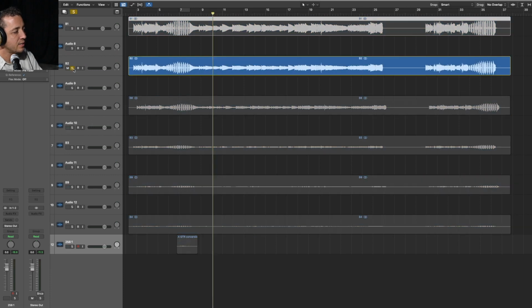This here, well, this is not too bad, but it's still a little bit too hot. You still want to turn it down because that almost clipped. You want to have a little more headroom than that. And right here, it actually did clip. For most of his levels, it's actually pretty good. But you want to have your gain set low enough so that it works for the majority of the recording, and also when they play something extra loud, like in a loud part, you don't clip. That's the most important part right there. No clipping allowed.